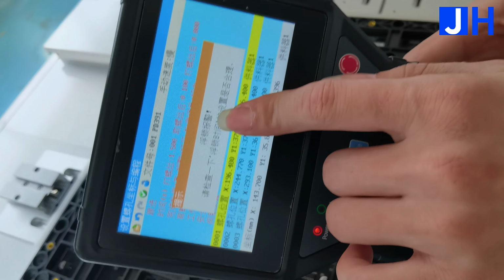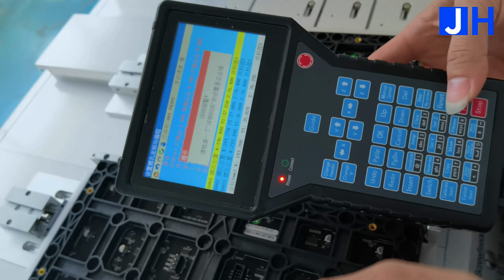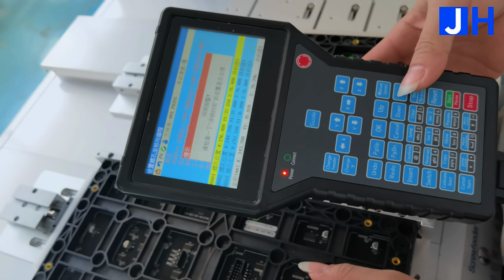The problem is that when the screw nozzle is lowered, it suddenly rises up and sounds an alarm. This shows a floating lock alarm, which means that the screw is not assembled properly. During the screw assembly process, the servo motor detected that the target torque of 30 had been reached, but the screw was not fully tightened, which triggered a floating lock alarm. When such an alarm occurs, we need to stop and check the cause of the problem.